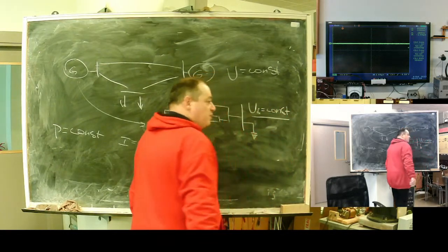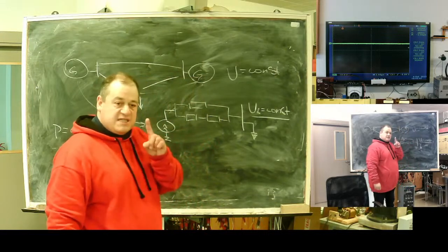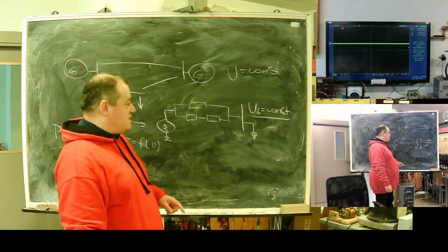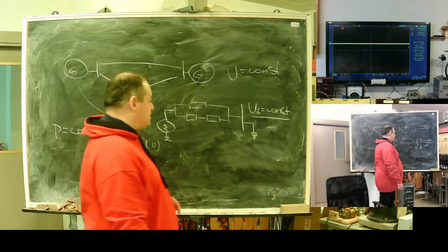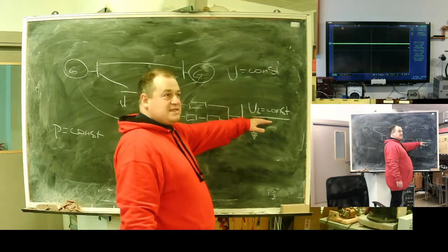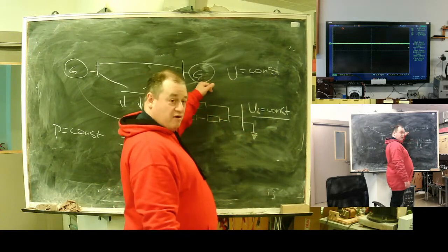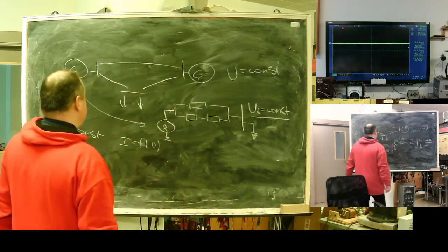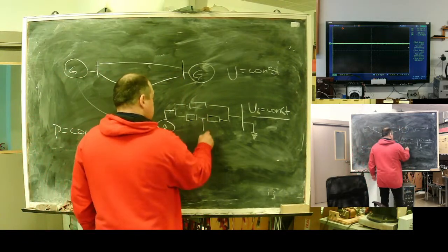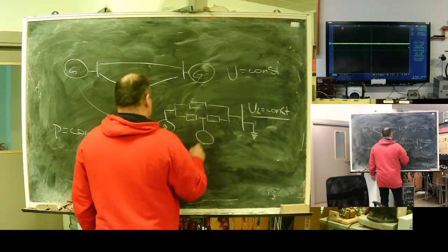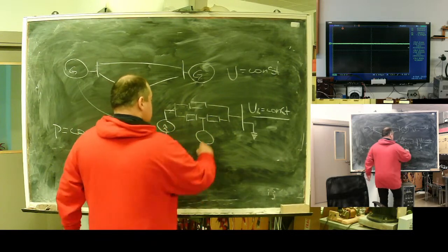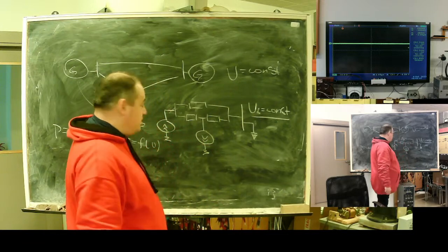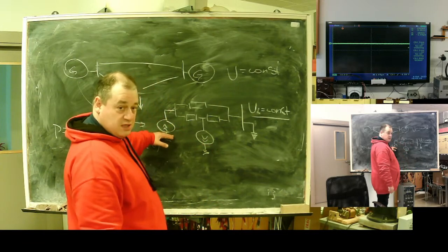It should keep constant voltage, not zero, but constant 600 volts, for example, or 610, something like this. It's a set point of the governor of the control system of this plant. Loads will be substituted with draining current sources. This one is a supplying current source.